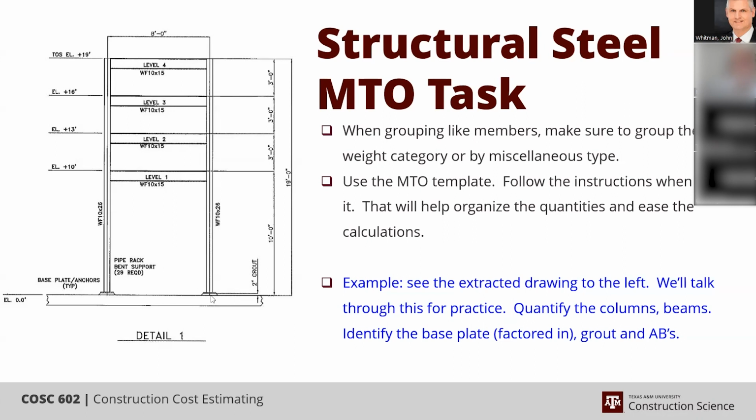So it's helping with that support, but it keeps moisture out from underneath there, and it helps with the load slightly, because concrete's better in compression than it is in tension. But again, you don't know how much grout you need until you know what the size of the base plate is.